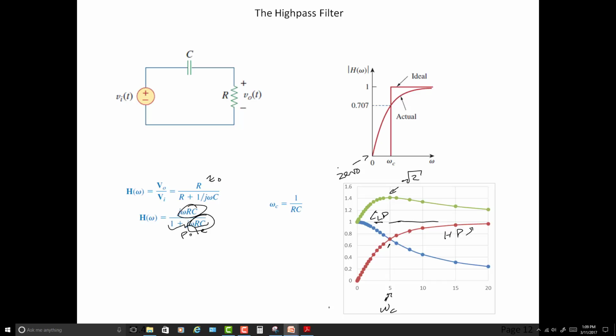So we'll be coming back to this, but what we're really seeing here is the sum of a low-pass filter and a high-pass filter, and you're going to get something like what we're talking about next, which is a band-pass filter. This, unfortunately, has both of them having the corner at the same frequency, and this is not very sharp. This is pretty sloppy.